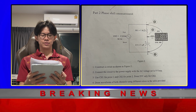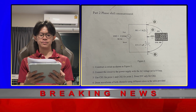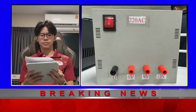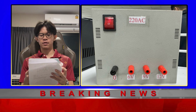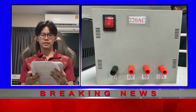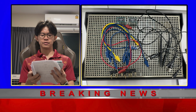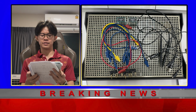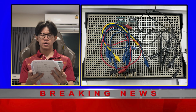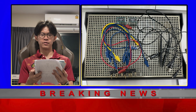So part 2 is phase shift measurement. Here is the diagram that we are going to build. The equipment is almost the same as part 1, but we do not need a multimeter and DC power supply for this one. We also need 2 probe wires instead of 1, and the resistor we will change to 1 kilo ohm and another 1 microfarad capacitor.